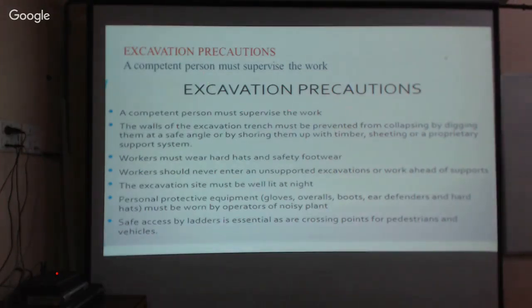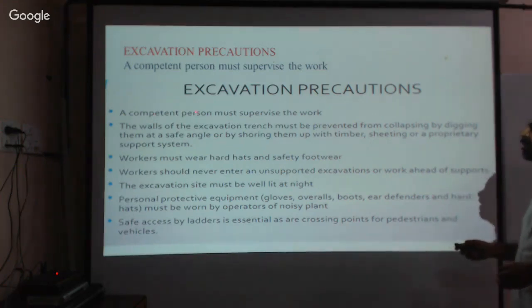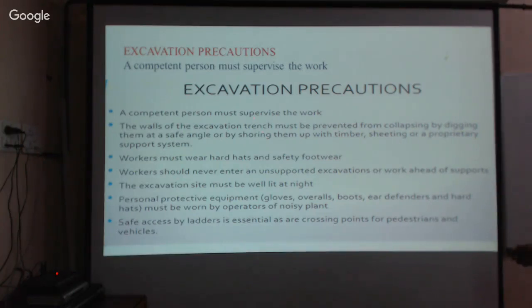Excavation precautions. A competent person must supervise the work. The most important is the competent person, the person who knows, he will understand. He should have enough knowledge to know when a collapse may happen, and be capable of understanding the situation in and around the excavation region.